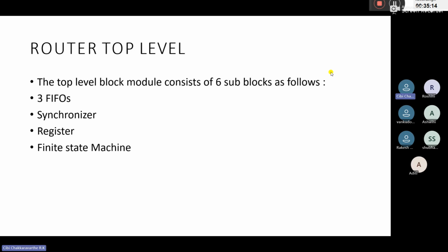Before writing something to a FIFO, which then delivers to the destination, as of now inside the router, we should check whether our FIFO is full or not, because if our FIFO is full, we can't write anything.